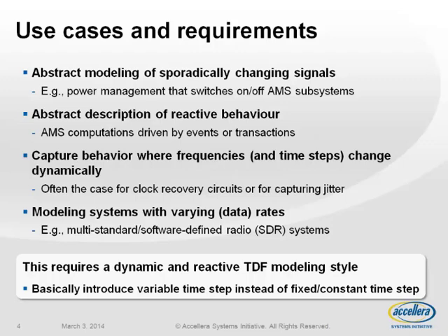So the need to be able to abstract the modeling of sporadically changing signals. So for example, to enable power management by switching on and off AMS subsystems, to be able to describe reactive behavior so that AMS models were able to get triggered by transactions, for example, so that there is a better integration possible with the SystemC TLM standard.